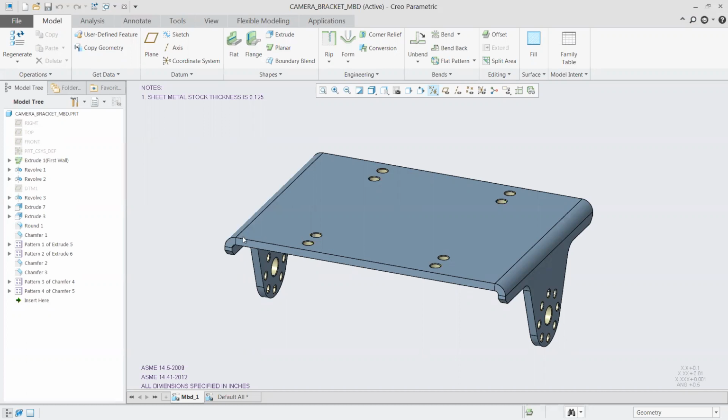So you do have different options. If we wanted to, for example, select all 4 different holes, then it could go through and reference that and build out a tolerance for that. I'll go through and show what that looks like here in the model as well. But in that case, it's simply, from a reference standpoint, only taking into account the one surface. But here I can also show what it looks like if you want to reference more than just one.